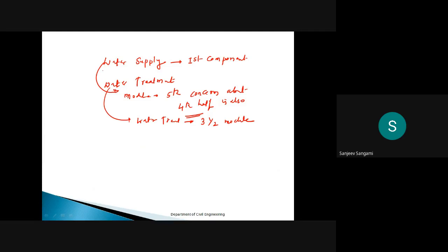So when you say your water supply distribution design is perfect, I can say so only if the user gets sufficient pressure. So how much is sufficient pressure? As per the CPHEO norms, 7 meters has to be maintained for the first storage building. Then only I can say my water supply distribution is perfect.